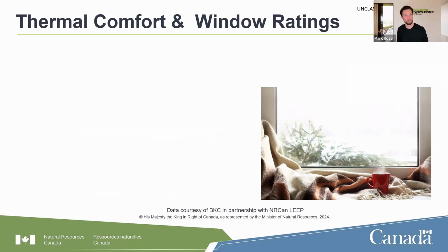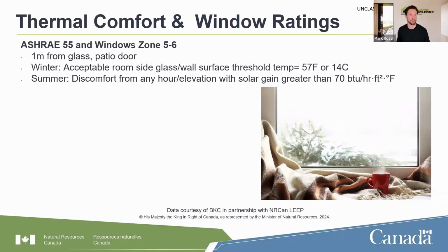And lastly, comfort. We can't talk about windows and not talk about their impact on comfort. And this case study is one of my favorites. This was one that was done, actually, I believe the anonymous individual in this example is Rachel Oding, Andy Oding's partner. And we were looking at the impacts from a comfort standard using ASHRAE 55, a comfort standard, on the impact on an occupant sitting 1 meter from a patio door, and trying to determine how many hours of discomfort there were using single, double, or triple glazed products.